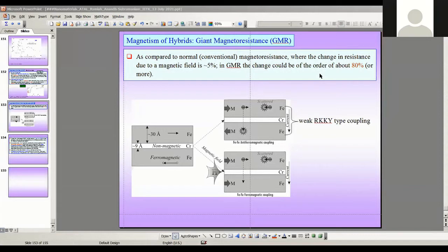Sorry, I have not read the latest literature on this. Functionally graded materials, I presume it might happen, but I showed you in the case of the nano layers, right? Nano sandwich layers. There, apparently the highest strength comes when you have one dislocation in each layer. And I'm sure even in these multi-layer structures, the inverse Hall-Petch relation is going to break down.